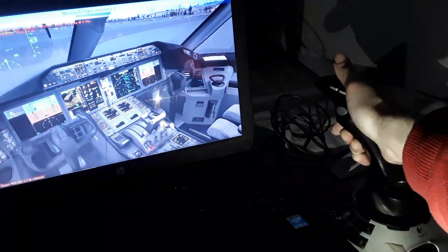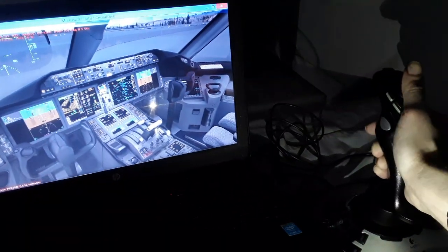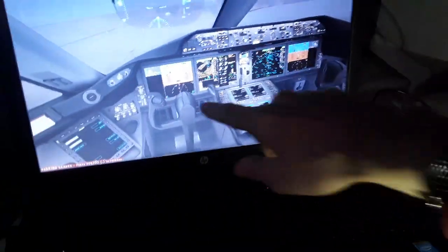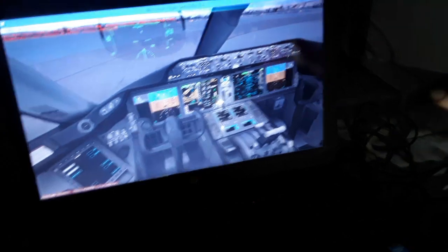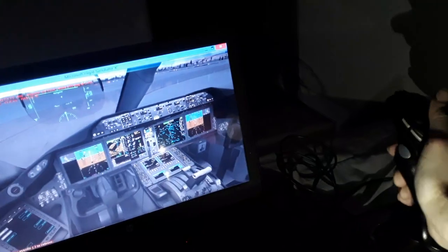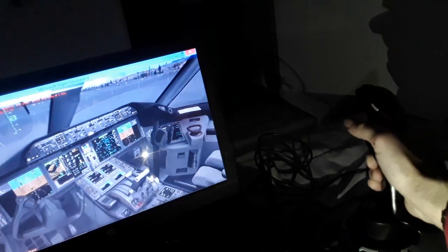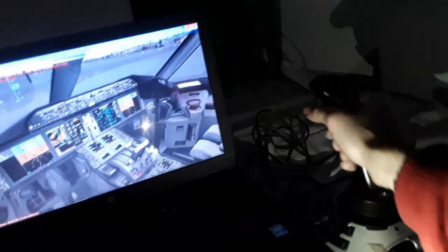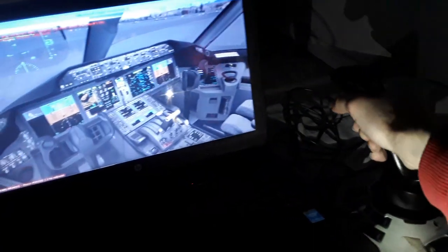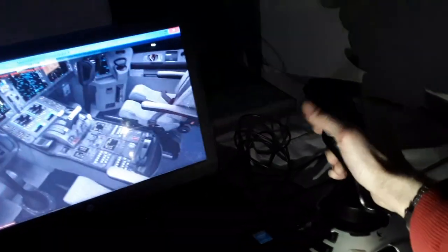Side stick up and down is the pitch axis. Also rudder pedals left and right over here, you can see, is the yawing axis or vertical axis. So elevator, climb and descent, ailerons and spoilers left and right turn, rudder pedals. You can see the side stick deflection is proportional to the yoke deflection.